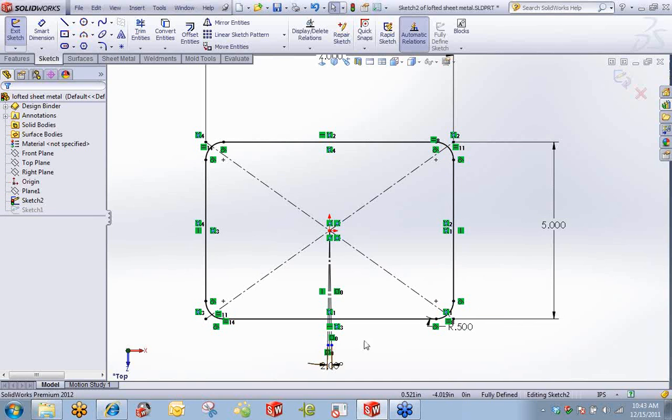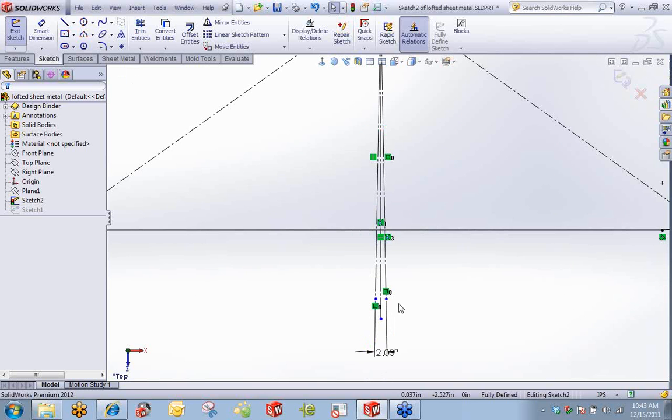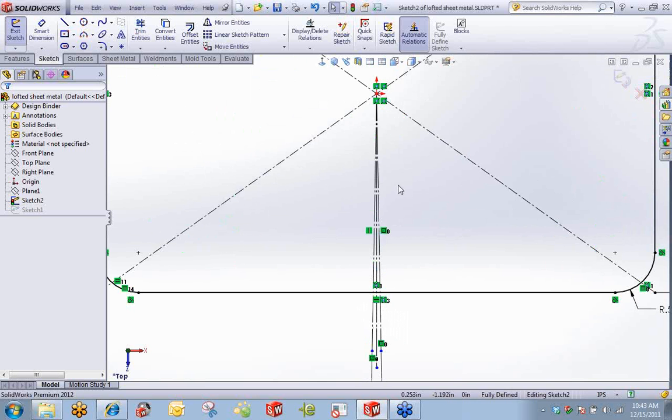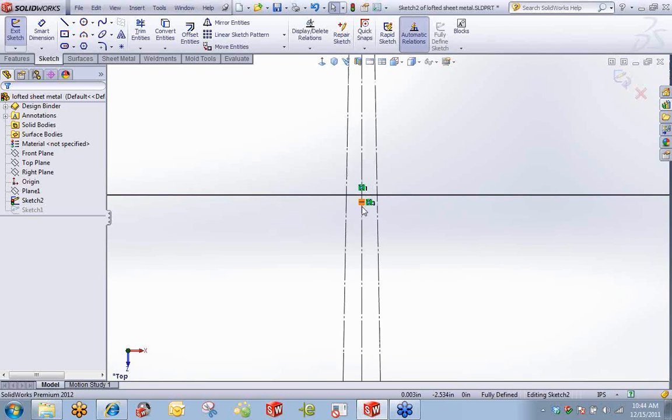All right, rule number two, it cannot be a closed profile. The profiles for your loft cannot be closed. Let me reword that. So you'll see here, this is the technique I've found to work pretty nicely. I'm not totally sure I want these at an angle. Maybe all three of these lines are vertical, maybe not.